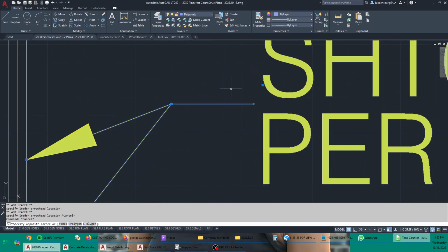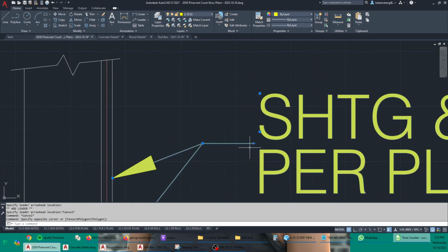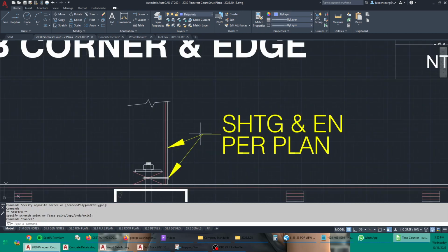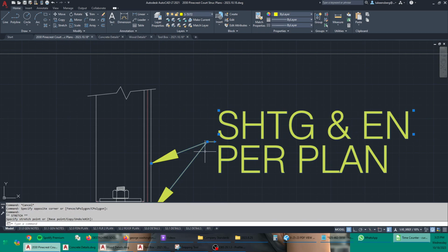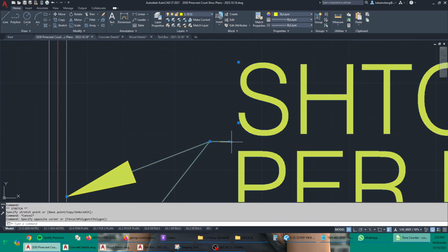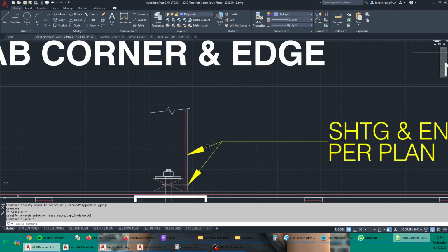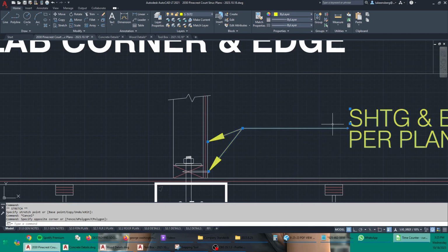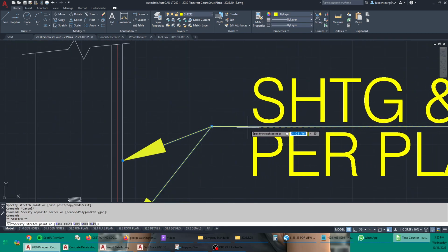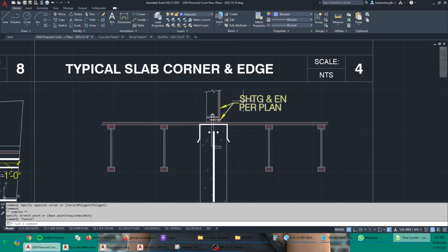being plywood or OSB sheathing. This landing, I like to have it be about as long as one of the letters is tall. Like that. It's about as long as the letters are tall. I've seen engineers, drafters do this. I don't think that's enough of a landing. I've seen some folks do this where they have this kind of thing, and I just call that flying away. I say, why is the label for this flying away from the thing that we are indicating? So I draw it like that.